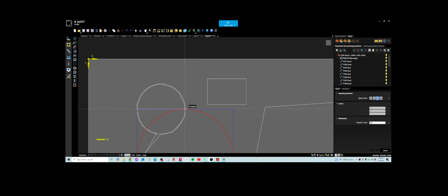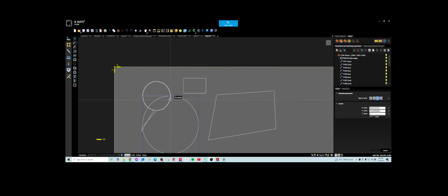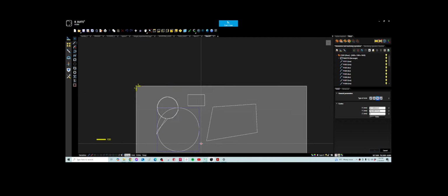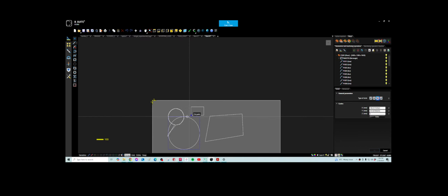You have the option, you find the other center of the line and you press OK. Either that, or if this wasn't closed, if this size was not the same as the other ones, the center wouldn't be the same, so it wouldn't work. You would have to make a line from center to center or corner to corner in order to find the center, and then you would make the circle there, right?